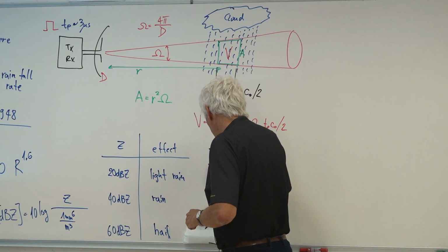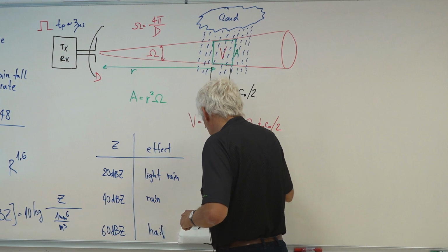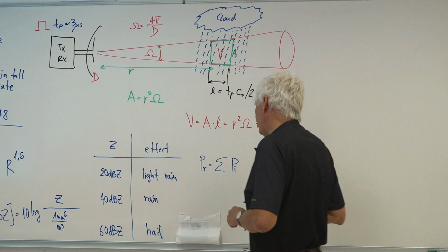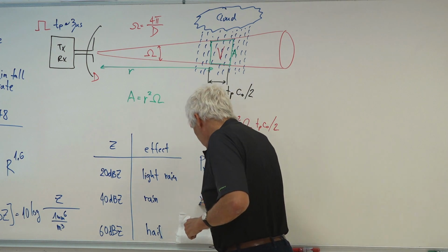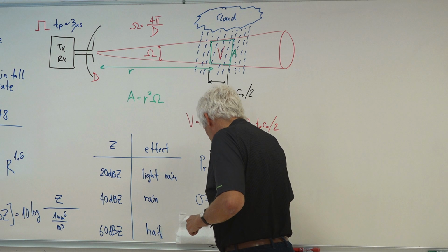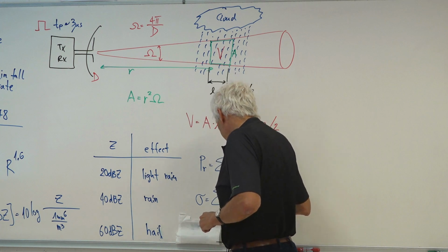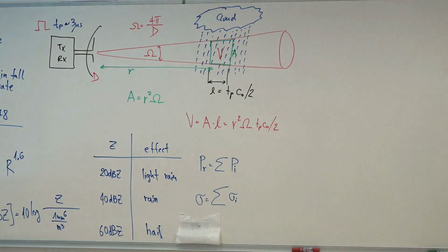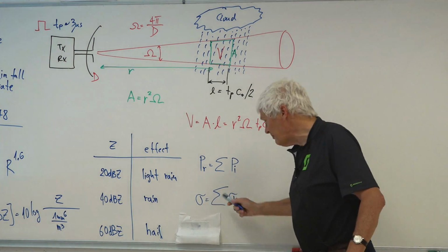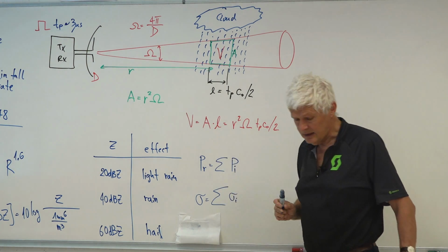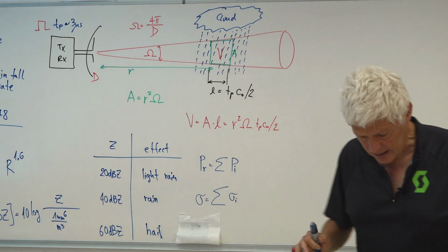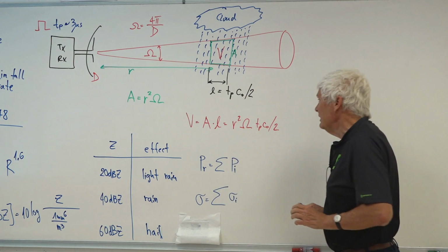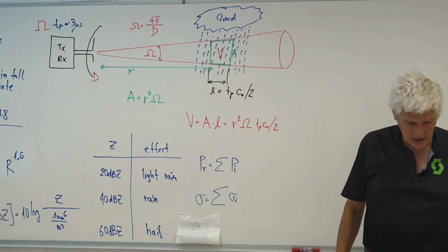The reflected power is simply the sum of each individual droplet, or the overall radar cross-section will be simply the sum of the individual cross-sections of the single water droplets. Cross-sections simply sum up because cross-sections are directly related to powers, and the phase is random, so only the power sums up. This reflection is really diffused in all directions.